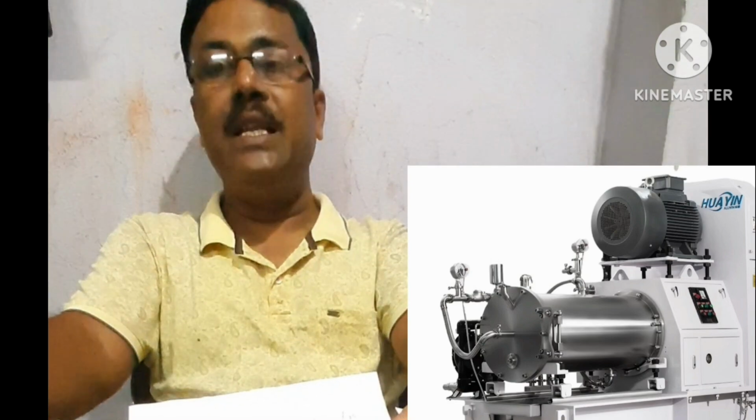After mixing, the charge is dropped into the second floor where there is a mill. After proper dispersion and milling, it is let down in the tank, and after tinting, the paint material flows down into the first floor where the packaging or filling is done for shipment or dispatch.